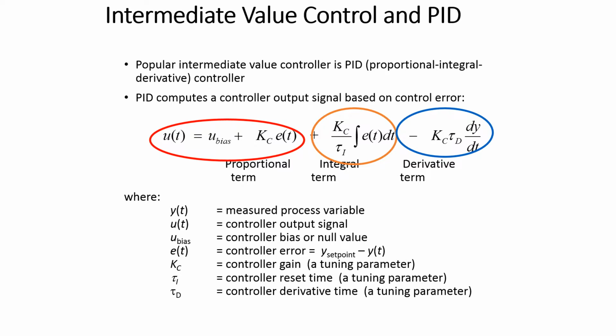We have a full PID equation here, and if you look at just the proportional part of it, you just take this term. Okay, so you have an error, which is the set point minus the process variable that you're trying to control. And that error, as it increases, then you add additional final control element output. Okay, so the output to the final control element.